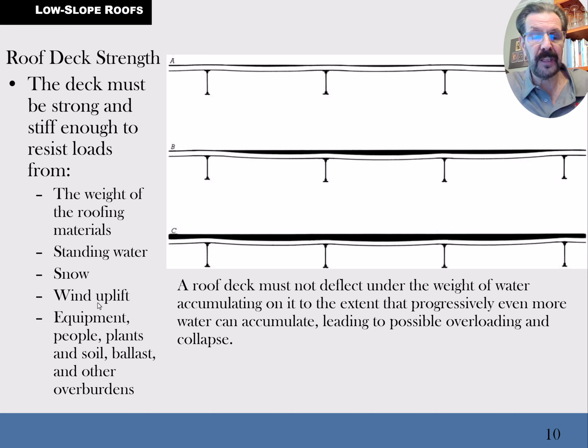that there's typically maintenance that has to go on. We often find abandoned buildings where no one's taking care of that eventually collapse because leaves blow up there. It's amazing. I've seen leaves get up on 10, 12-story buildings and clog drains. And so it can get on the roof of lower buildings very easily. They just blow around, they end up collecting and then eventually building up around the drains.